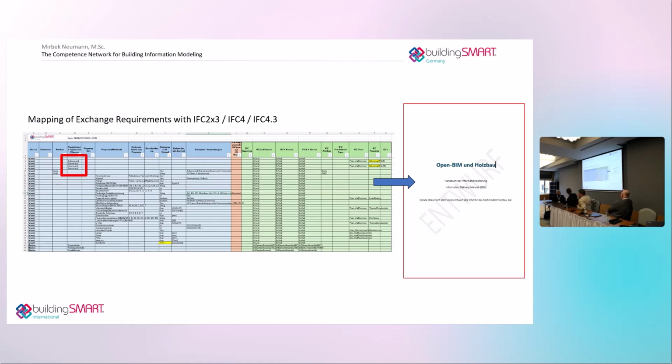Well, you don't have to reinvent the wheel. You have fire safety in the IFC schema also as a part of manufacturer information. That's even better described in the schema. It's Pset_ManufacturerOccurrence or Pset_ManufacturerTypeInformation. They go through information about a manufacturer, including assembly-related property sets.